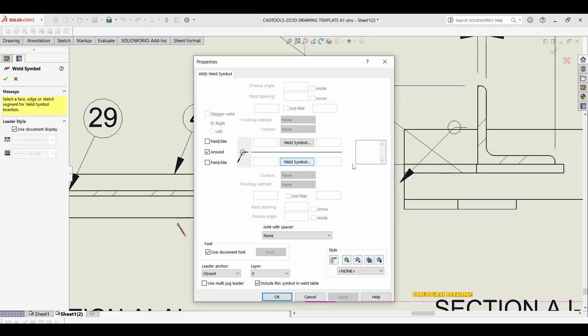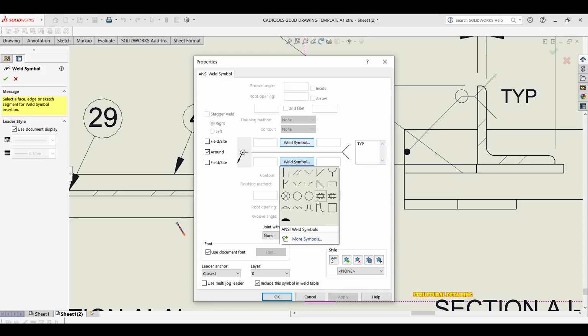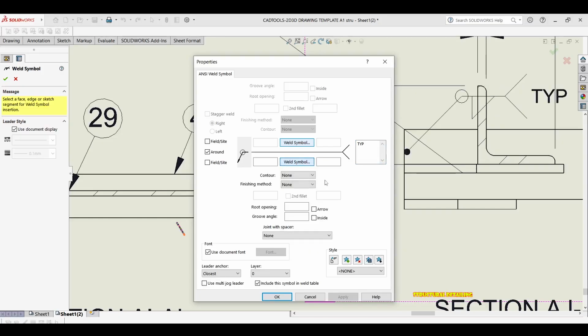I want the all around weld, so I want it to be welded around. Or you can put a fillet weld this side and that side. Okay, I guess whichever one you think is strong. And I want to say here typical, and yeah, it's a fillet weld, right?